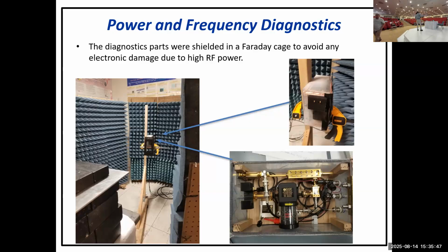This is what you do for down conversion. You have a lot of components, and these components are semiconductor, low power. So you need to attenuate the signal so hard, because we're talking about megawatts of power incoming, and your local oscillator is microwatts. If you have watts coming from one side and microwatts from the other, you're not going to have a balanced mixer or a difference. You'll receive only one of them and the other will be noise. So you need to attenuate your high power signal a lot.